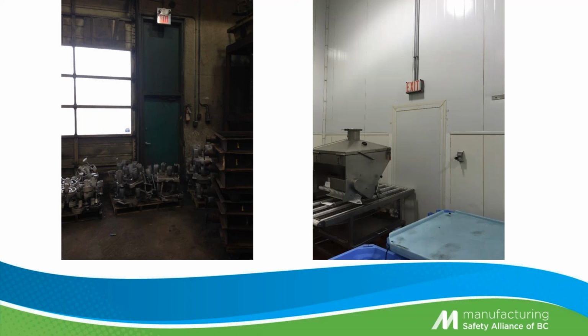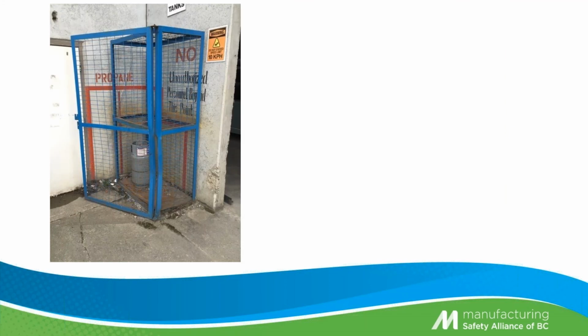Here we have a fire exit that's blocked. So if the lights are out and you have to head outside and the power's gone, that's a potential hazard. Our next one was in a food processing place. They deleted this door, but the lighting was still operational. So if they lost their power and there was an emergency, that would illuminate, yet there's no door, there's no handle, and it's blocked. You could potentially have people fighting to try and get out there, only to find out that it doesn't go anywhere and there's no handle. Here we have a propane tank storage.